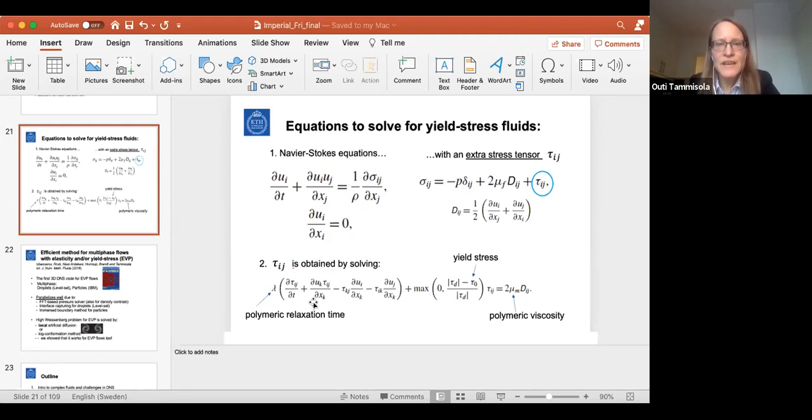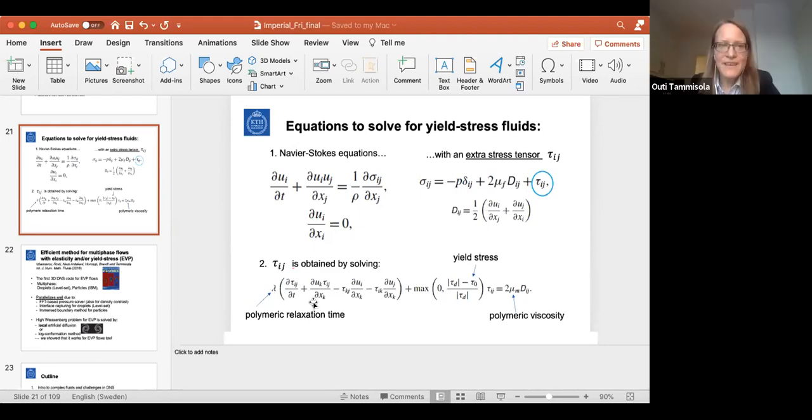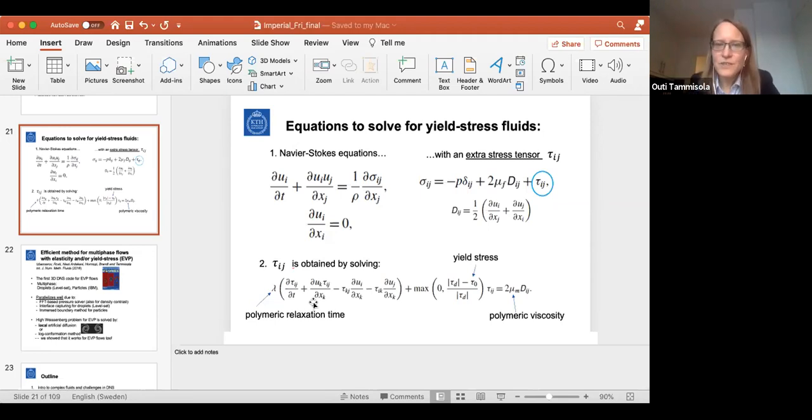If you think about the Bingham fluid, you can model a Bingham fluid, physically, one way to model it is a Papanastasiou model, where you basically make the solid a very, very high viscosity fluid. That's what I was thinking. Yeah, I thought you were doing it this way. Sorry then. No, it's no problem, but this is a good question. So actually what we do is we say that it's an elastic solid. So it's not a fluid with a very high viscosity. It is an elastic solid.